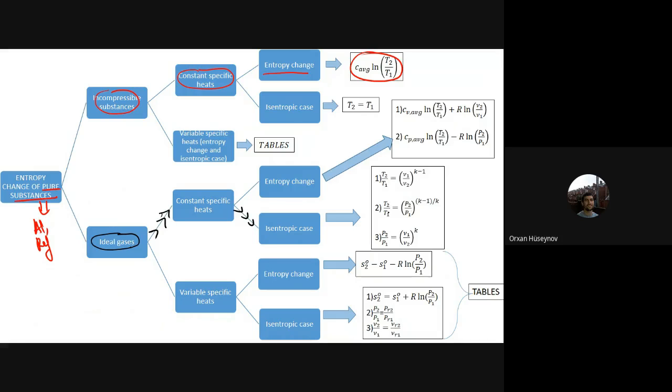Okay. The temperature ratio is equal to the pressure ratio. So you have this one, or that one, or that one. Whatever option is best for our case, we will use it. So in our case, T2 and nu2 are unknown. Therefore, this formula doesn't help. And for the T2 here, it is okay, but we don't have any unknown here. Therefore, we can use this option. And P2 is okay, P1 is okay, and nu2 is unknown. Therefore, we can use this option.